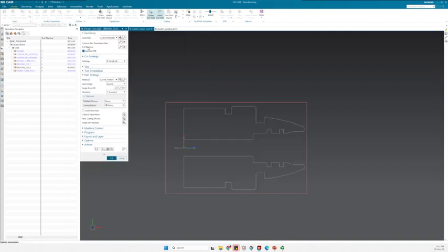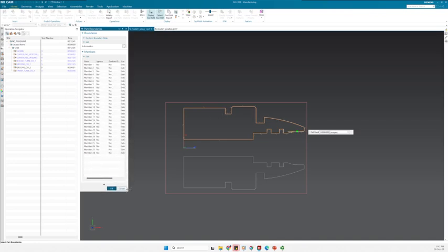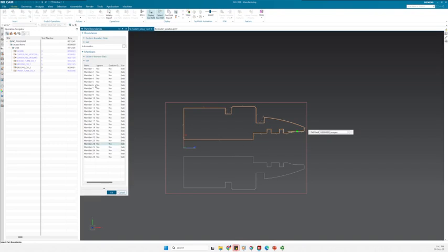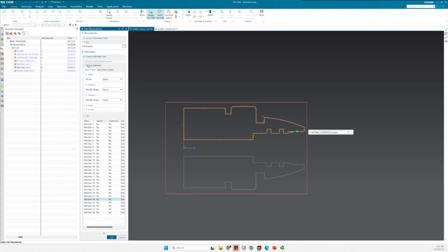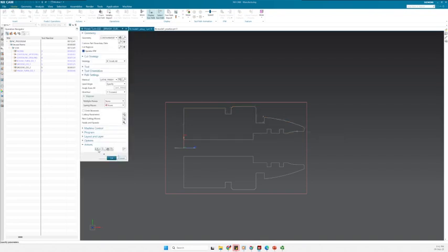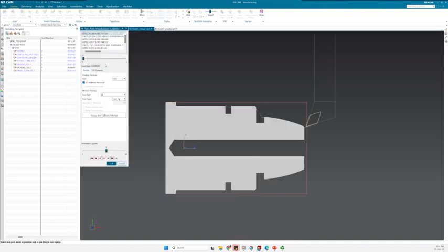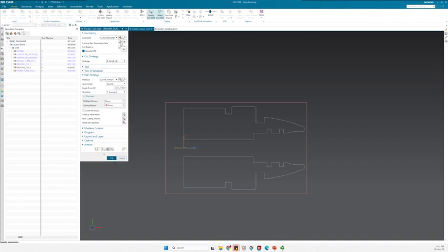So for this one, I need to go to, yes, here, custom boundary data. So all of these points that you can see are now called a member. And I can see the list of the members here, or I can just simply click here. So this member, I can customize and say ignore this point. And currently I only did that, and then let's see if it solves any problem. Not much, so let's do it again.